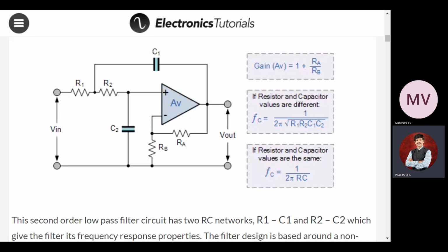Similarly for frequency, the knobs in your function generator, CRO, and also the RPS, regulated power supply, are used to increase or decrease the voltage or the frequency. All of them work with the same principle: as I keep rotating clockwise, the resistance value reduces, and as I keep rotating anti-clockwise, the resistance keeps increasing. These are simple potentiometers. Some move freely, and some move step by step.